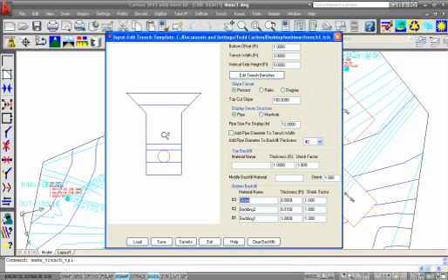Okay? And then, so what's really fluctuating is that these amounts are locked at the top, at the bottom. The stone is fixed. The middle bedding, bedding 2, is going to fluctuate as the pipe gets bigger or smaller. And then this middle here will fluctuate depending on how deep the trench is. So that's going to be our middle, or this was gravel. That's going to be our middle backfill quantity, and we'll just call it fill.